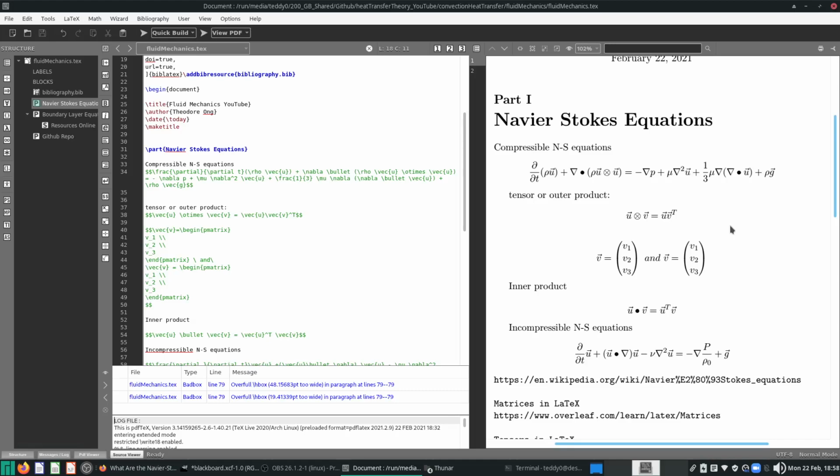How much net flow is there into or out of the control volume? It's very similar to this: del by del t of rho u is how much mass is going in or out of the so-called unit volume. And this divergence of u is similar in concept: the net flow of fluid in and out of the volume.